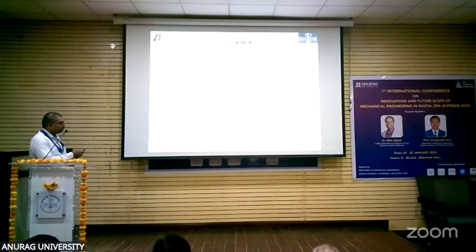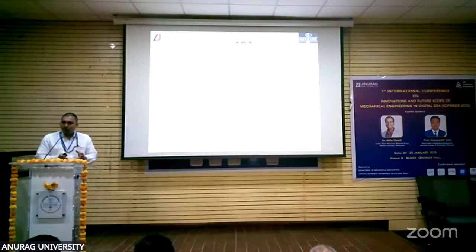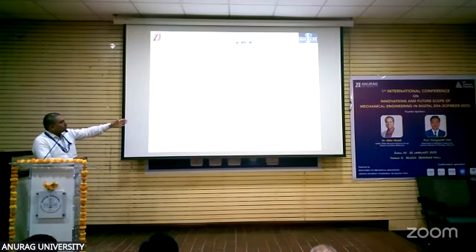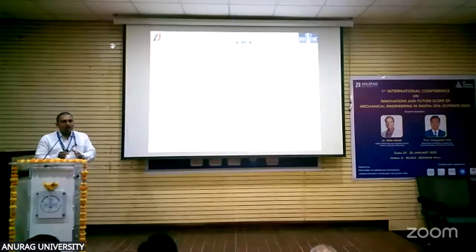So, in the last 2 minutes, this is the dust effect. For 31 days, we conducted an experiment on dust. Mainly we observed that the plant was located on the fifth floor. Very few sand particles accumulated on the plant, but majorly we observed bird droppings. Birds were placed there, and bird droppings were the main problem in that area. So gradually the performance of the plant decreased, and in total over 31 days, we observed a 13.9% average reduction in the plant.